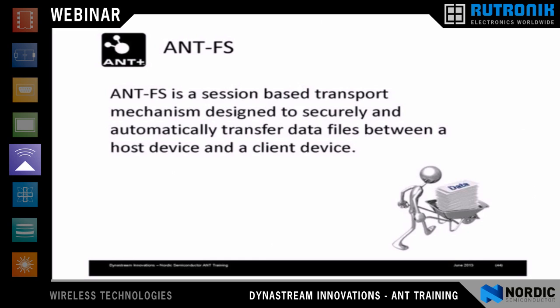So I mentioned ANTFS earlier. That is the file share. That's what ANTFS stands for. It's a session-based transport mechanism. It's really a state machine that allows you to use a beacon from a receiver, connect with the beacon when you need to on the transmitting device, and then go through an authentication process before you're allowed to transmit data.